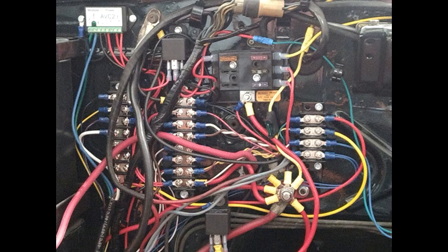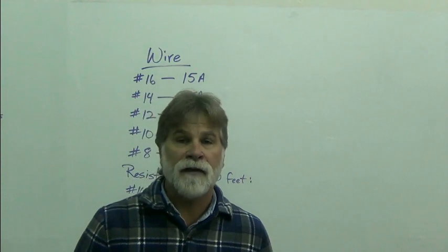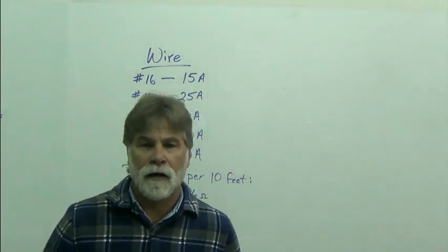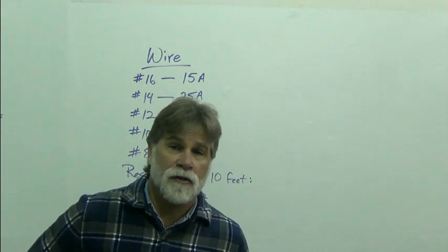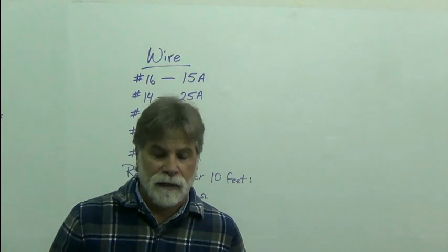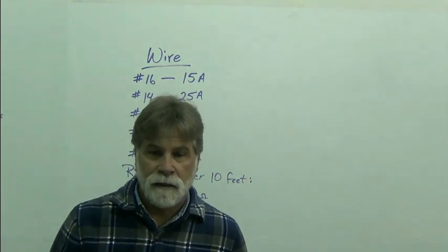There are solid strand, multi-strand, braided strand, insulated, non-insulated, solid color insulation, multicolored insulation, and you have very fine wire to very heavy cable. Lots to choose from. Which you choose will be based on the application. Be mindful of the wire, and mainly the size of the wire, because using undersized wire for a certain load can cause a problem. And so let's talk about wire.